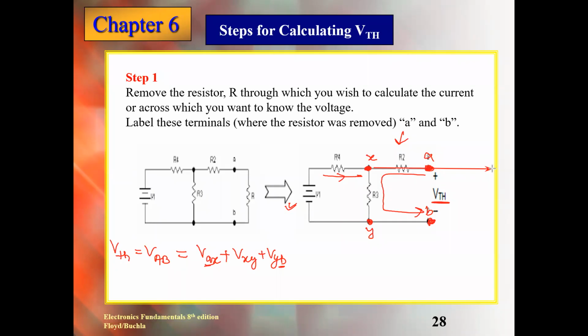What is the rule for current to flow in any circuit? A closed circuit has to have a closed path. So it cannot go there. All current will pass here and go here and go here like that. So no current will go here. Reason? Because here is open. Getting the idea? So no current is flowing here, meaning I is equal to 0.